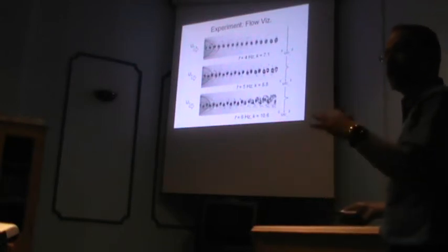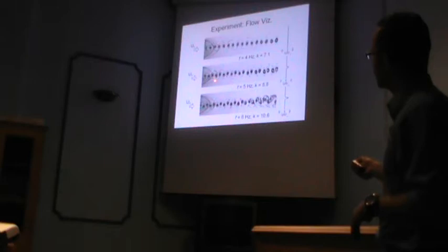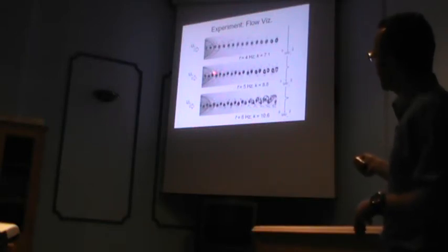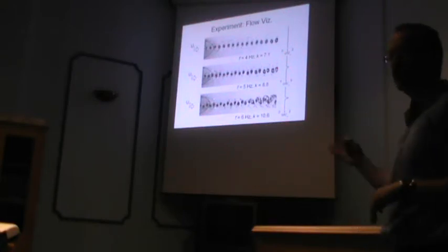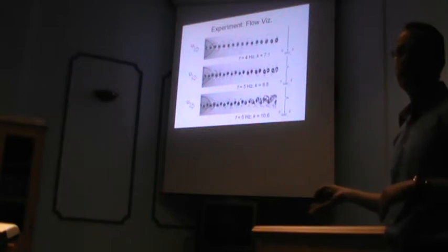If you continue and you actually oscillate it even further, then you get the positive vortex to move up and the negative vortex to move down. And what happens then, the top vortex induces velocity in the forward direction. The bottom vortex induces velocity in the forward direction. So, of course, this is unsteady flow, but in the net, you actually get a jet behind the airfoil instead of a wake.